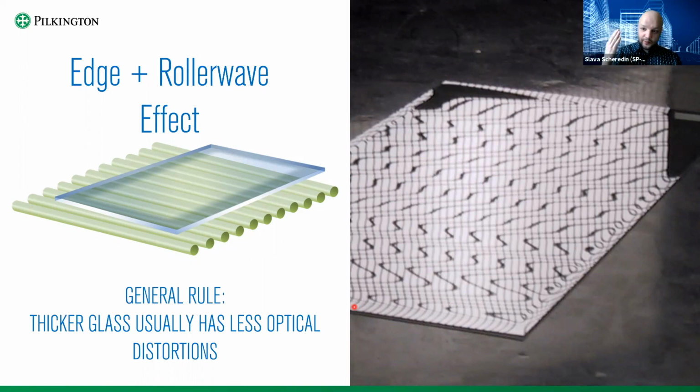So if we're taking both facades of equal quality, one of light reflection of 15, another of light reflection of 30, then you will get two absolutely different facades from visual point of view. Again, less reflection, less to worry about distortions. So thicker glass, lower reflectance, proper design, good processing.